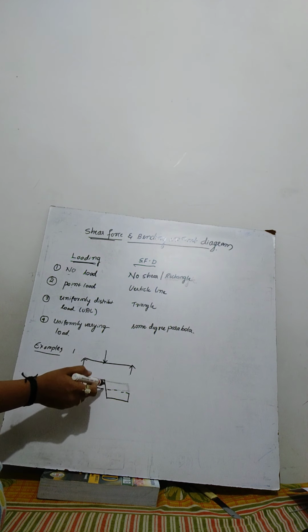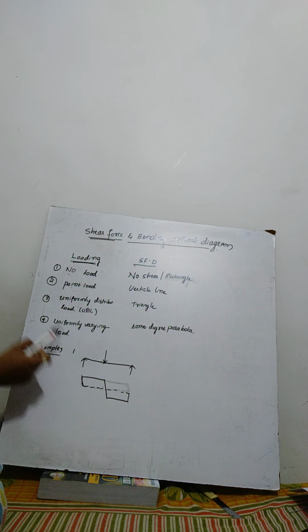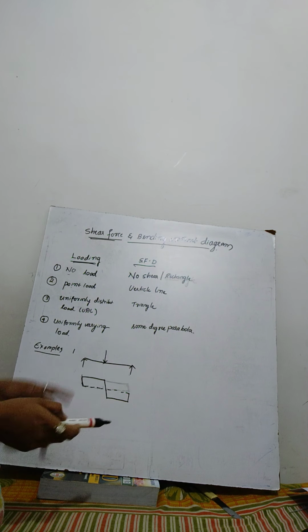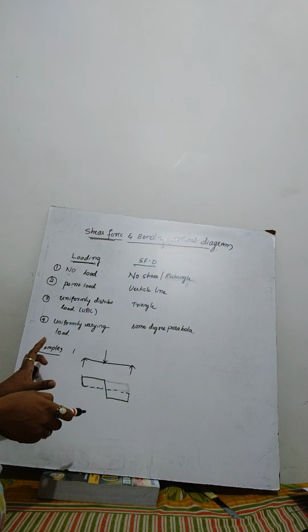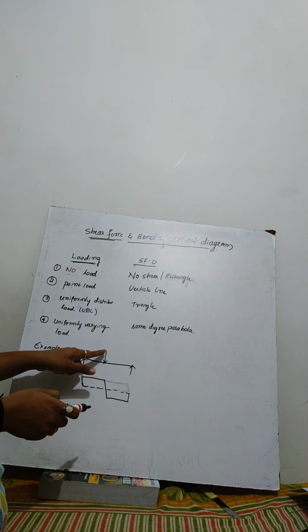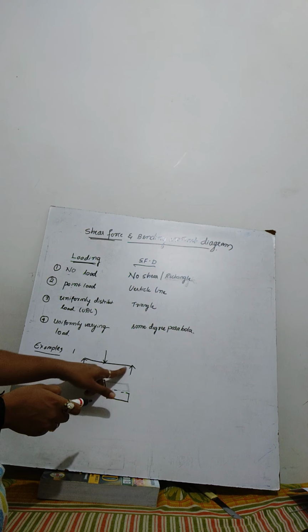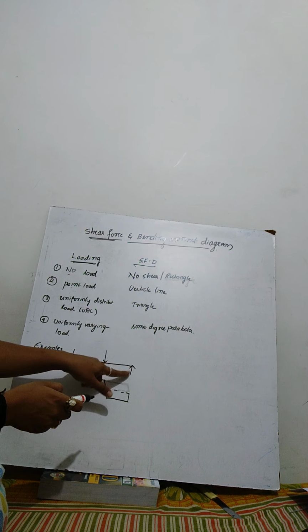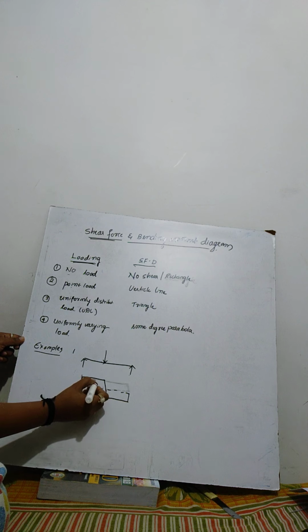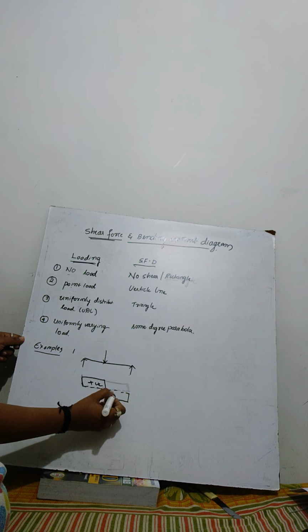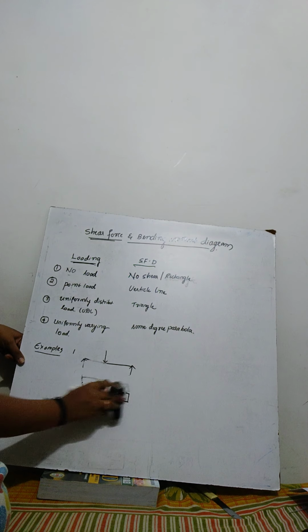If there is a point load, then see, this is upward direction. From this reference line I'll take upward. Then here there is no load. That means here it is plain, a single line is running. That means no load is acting there. So I'll draw one straight line. Then it is a downward symbol, so I will take this line downward. And here there is no load, I'll go straight. Here there is a stop, I'll go up. This is how your shear force diagram looks, and this is your positive shear and this is negative shear. Okay. Next is UDL.